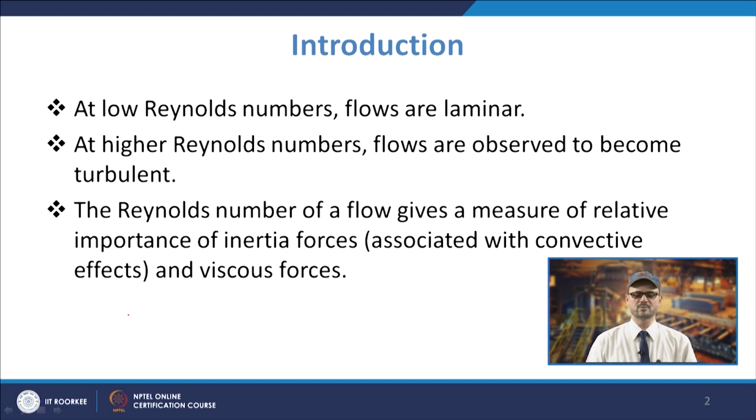Now, the Reynolds number of flow gives a measure of the relative importance of inertia forces and viscous forces. As we know, the Reynolds number is inertia force upon viscous force. So, if it is of smaller value, it means viscous forces are more dominant, and if the Reynolds number is very high, it means inertia forces are dominating.